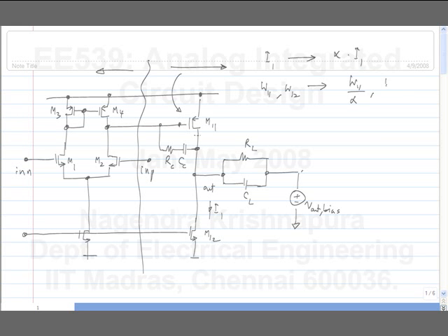If it's in strong inversion, the GM will be maintained. So what happens because of this? Yeah, it will go down, but is there some disadvantage that you see? See, finally I want to make an op-amp which is stable and which satisfies my speed constraint on omega u. So what will change because of this?